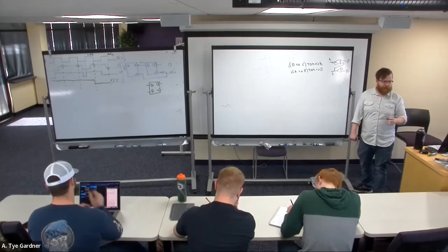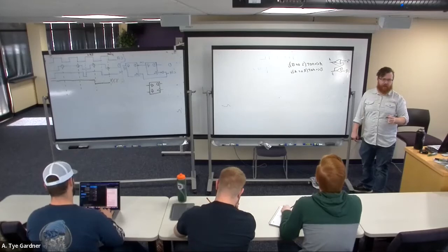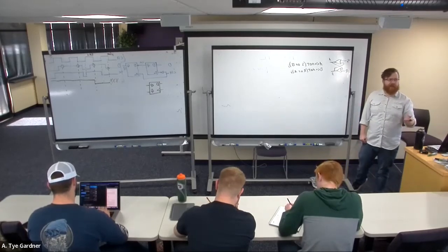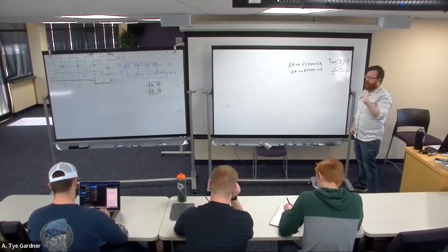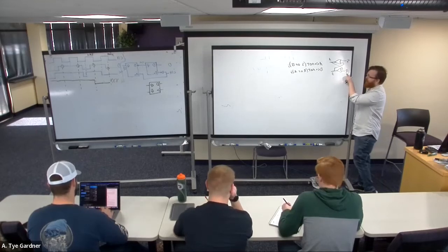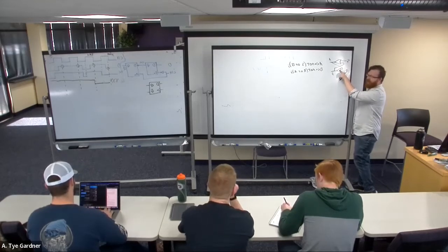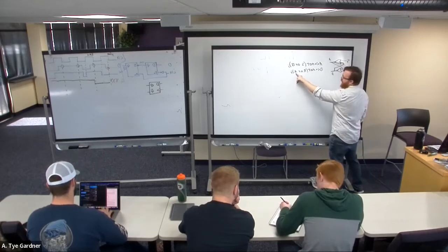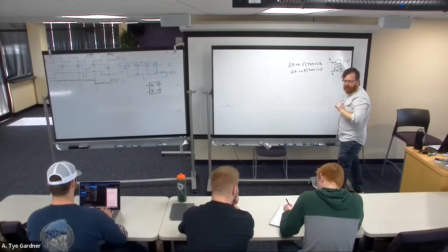Well, that still doesn't give me my Q, right? Because there's a quirk with VHDL that it really doesn't like it when you plug output ports back into input ports, right? Because my input ports are R and S. So it's not going to like this. It does not like outputs on the right side of assignment statements.